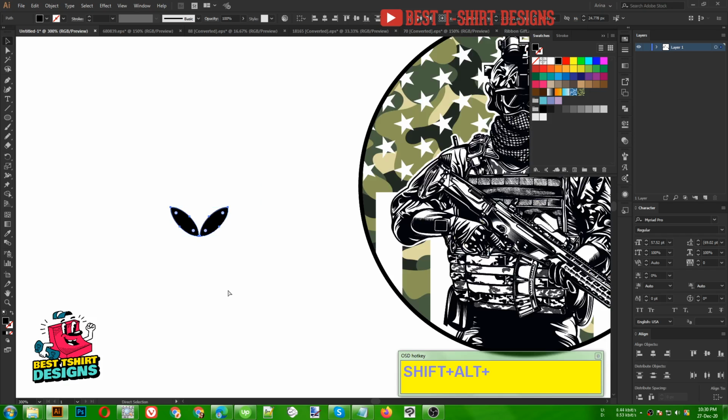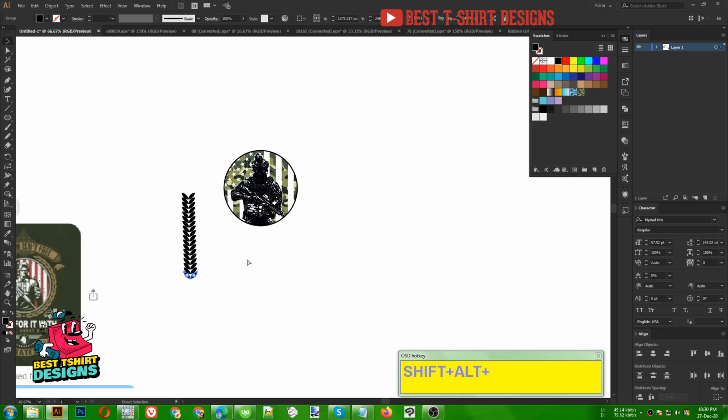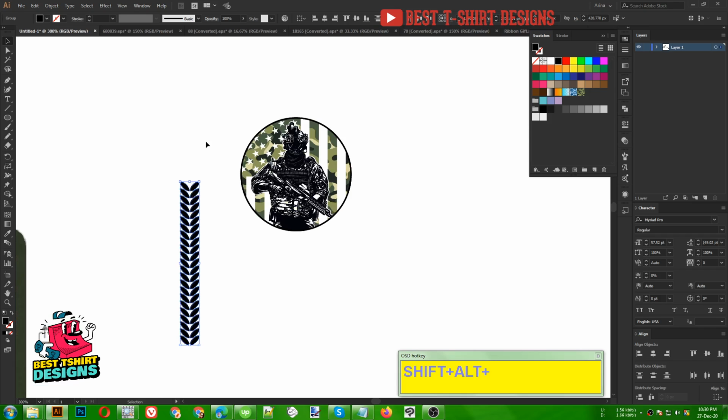I need to make it a group here, so Ctrl G for group. I'm bringing a copy down. Now I can press Ctrl D. Keep pressing Ctrl D until you get some copies here. We don't want to make a pattern brush here. We will make an art brush here. So I am just aligning it together.